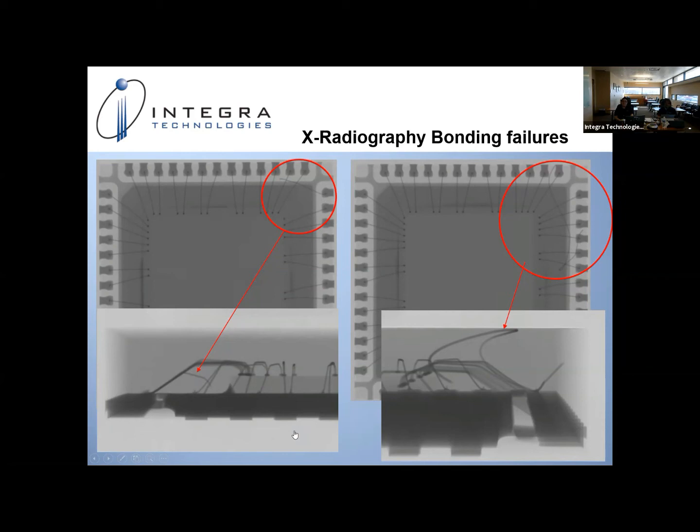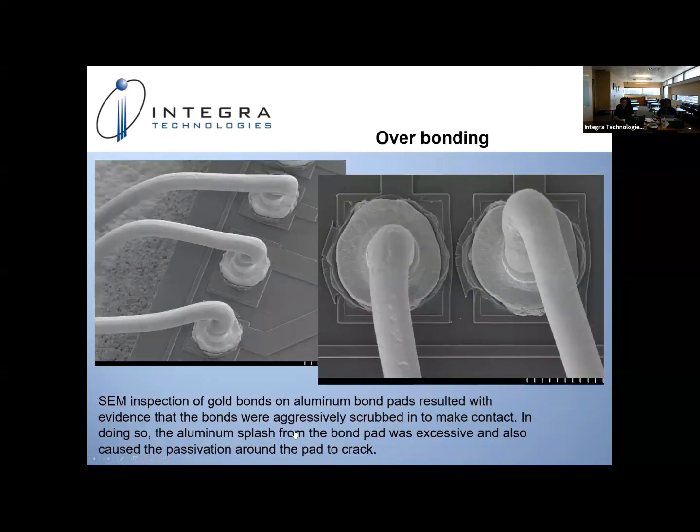You can also see this in the side view, which the arrow is pointing to. On the right-hand side image, extraneous bond wire material was left in the plastic encapsulated molding compound. You can see it running across several bond wires in the top side view. In the bottom side image, you can see it in the side view, kind of floating around, if you will. It's truly embedded in that plastic molding.